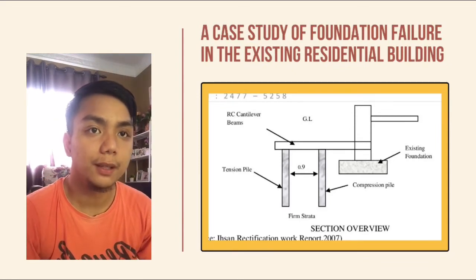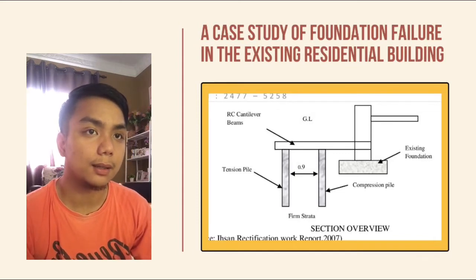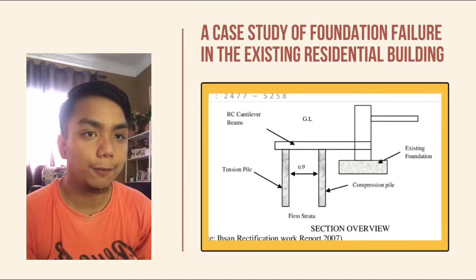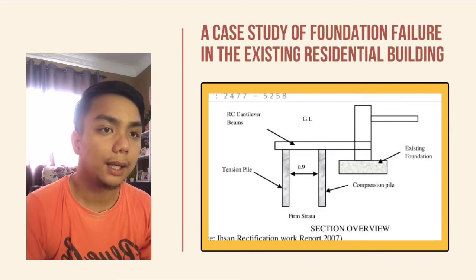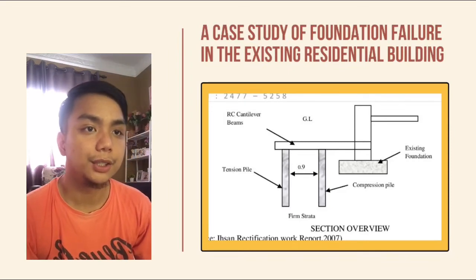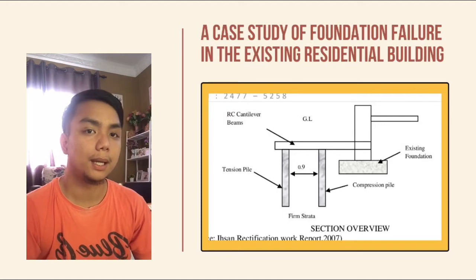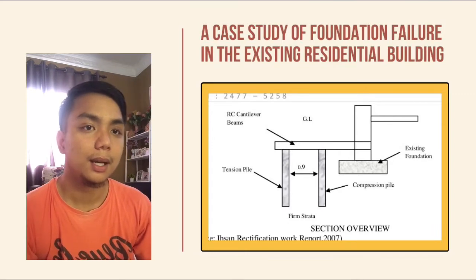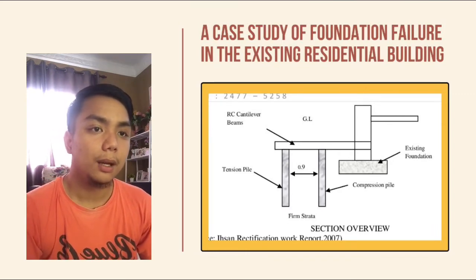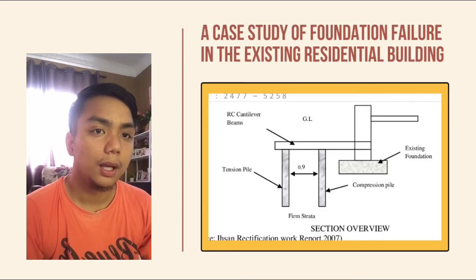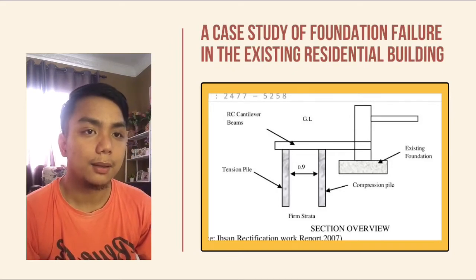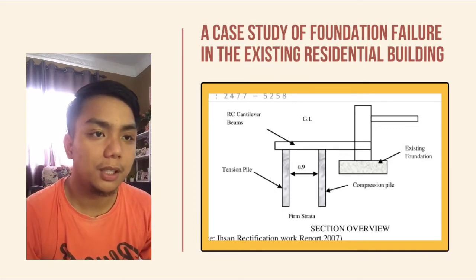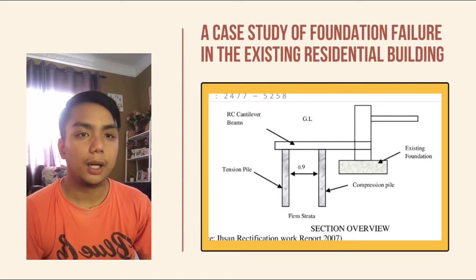Number 2. First, the location of the crack is as important as the physical appearance. Foundation movement often results in cracks at weak points, such as window openings and doors. Second, foundation movement tends to distort openings and often causes doors and windows to stick. In some cases, the distortion may also affect partitions, ceiling, floor, and the roof.